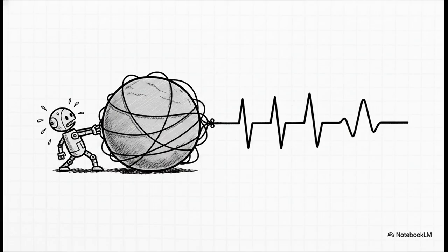That tiny amount of current has to overcome the capacitance of the entire bus. If you surpass the strict 400 picofarad bus capacitance limit, those crisp, beautiful square digital waves turn into sluggish, distorted curves. The rise and fall times get completely destroyed, and suddenly, that precise bit-by-bit duel we just talked about completely falls apart because the chips just can't accurately read the voltage levels anymore.